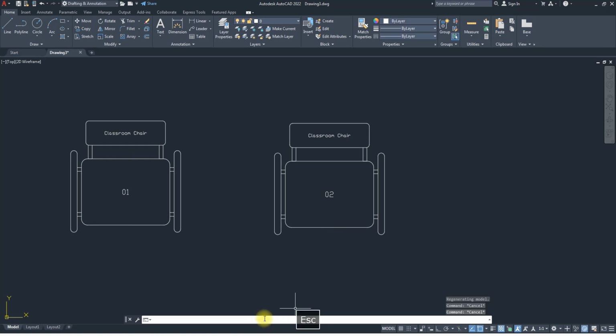So then we now have this last one, Batman. I know that's what Esther is waiting for, Batman. So Batman is an acronym for Block Attribute Manager. That Block Attribute Manager allows us to do a whole lot of things to change the whole structure of the block. So when we say we are changing the whole structure of the block, whatever change we make to a particular field or a particular attribute will have effect globally, unlike edit attribute that we did. You know, edit attribute only affects that object you select. But if you use Batman, it's going to have a global effect on all the instances you've added.